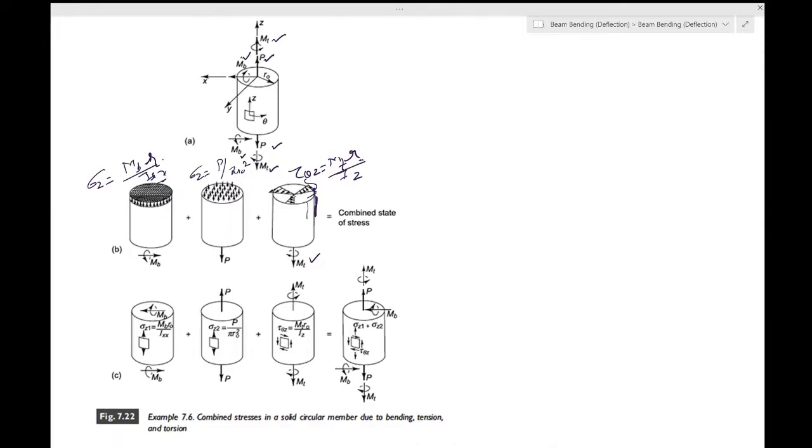Now that is shown in this figure. Now in C over here, you have written down these values and you have done that on the surface. So everywhere r will be replaced by r naught. Okay, and you show the individual stresses acting on an element at y equal to r naught. At this element, the distributions A and C have their greatest value, and there is a reason why we are trying to do this at y equal to r naught. The reason is that this stress will be maximum at r equal to r naught, and this will also be maximum at r equal to r naught.